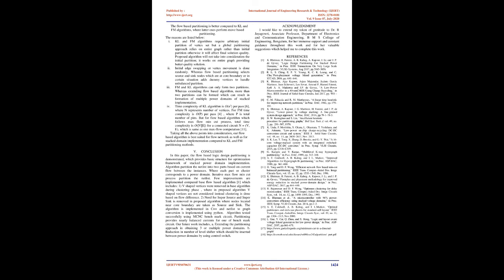The flow-based partitioning is better compared to the KL and FM algorithms, where the latter perform move-based partitioning. The reasons are listed below. 1. KL and FM algorithms require an arbitrary initial partition of the vertex set, but a global partitioning approach relies on the entire graph rather than an initial partition, otherwise it will affect the final solution quality.